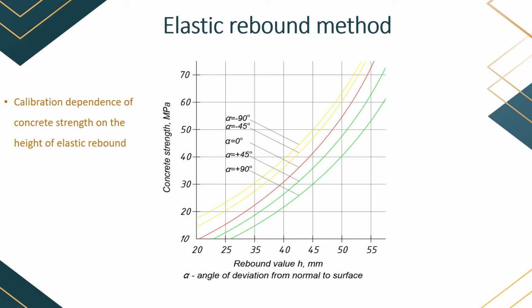The electromechanical converter receives a signal about the energy of mechanical impact on the concrete surface. In other words, the potential energy of a striker is converted into kinetic energy when it is transferred to the particles of material and partially returned to the potential energy of the same striker during the rebound. In this case, the device directly measures the pulse energy at the moment of impact, obtained in the form of an electrical signal. The advantage of this method over the elastic rebound method is the possibility of allowing deviations from the plane of the concrete surface, while maintaining the accuracy of the result.